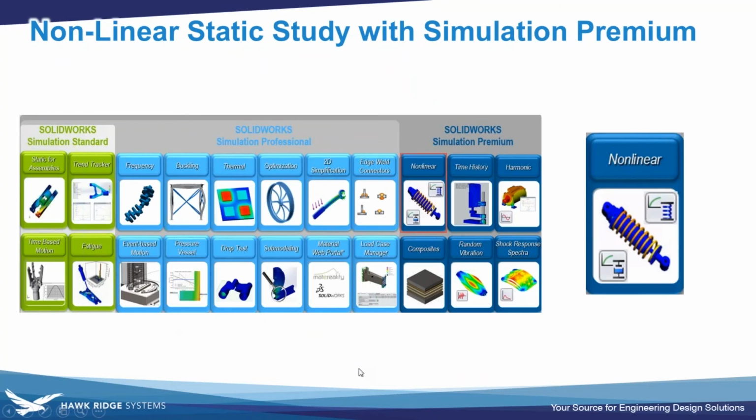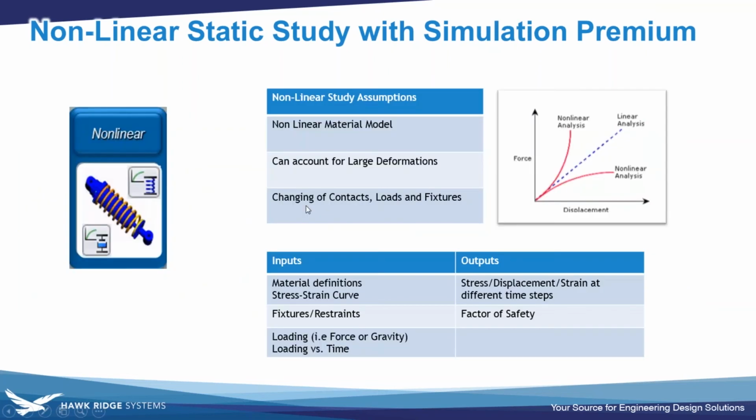So I can take a look at this and it can show us, is this deforming too much? Right now we're looking at an exaggerated case where the deformation scale is set to 1,600 times, but we at least get an idea of how things are going to be deforming. And now we're looking at a displacement plot where I can actually animate this and see, based on that acceleration that I define, how is it going to deform? Well, what are the things that I might be concerned about, maybe some of these components here.